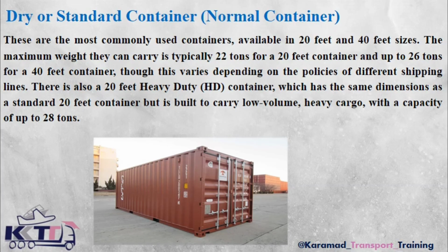There's also another type of 20-foot container, which is called a 20-foot HD or heavy duty. This type of container differs from the standard 20-foot container in that its body and floor are made of stronger and more durable materials, making its structure more robust compared to a regular 20-foot container. Therefore, these containers are used for loading goods that are heavy and very weighty. For example, stone, which a regular 20-foot container cannot withstand the weight of. If you load this cargo into it, the container floor might give way. That's why you always see that for transporting stone and similar goods, heavy-duty 20-foot containers are used.